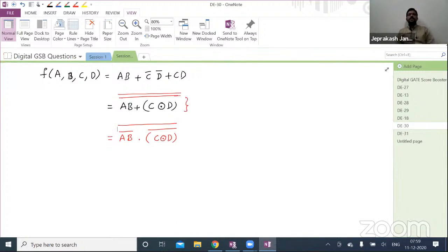Right. Okay. Now here you're having AB bar. Just 1 second. So just now we have mentioned, from where you are taking the output in CMOS logic, by default you will get the complement version, right? So under the complement you're having what? 2 variables, A and B. That means you require 2 NMOS transistors in series. See here, very simple. Whenever you're having logical AND, that means we will connect NMOS transistors in series. Exactly opposite, will connect PMOS. That means 2 PMOS transistors will connect in parallel. For logical OR operation, under the complement, will connect NMOS transistors in parallel.